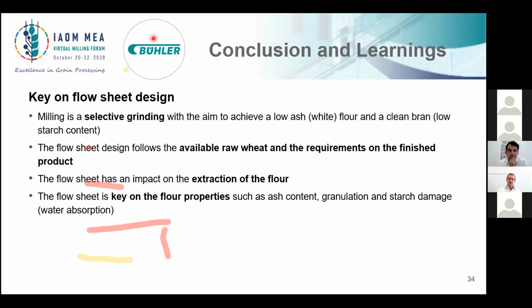If not, it is definitely an issue that changing sieves needs a downtime of the mill. So we need to stop the mill, open the plant sifter, and get it ready for the next. Either the flow sheet can be designed with flap boxes, so you can change the flour sieves by different streams, adding through a flap box, or it needs a downtime to change the sieves.